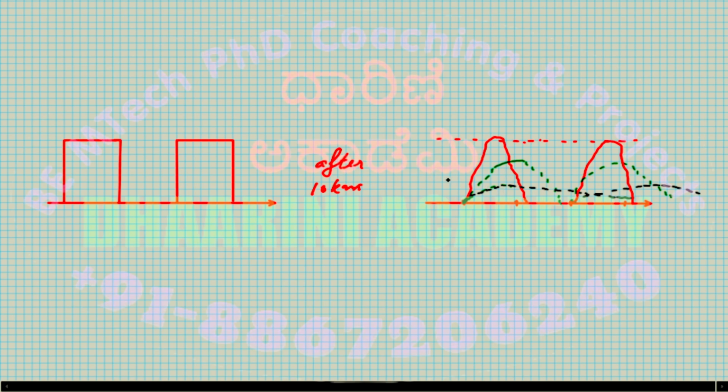Whenever this signal is given to the detector, it may have a threshold to compare. Say the threshold is 50%. If it is more than that, it is 1. If it is less than that, it is 0. Let us say. Now you see, your signal is not at all crossing the threshold. Correct? So everything will be detected as 000 only. So you lose your complete information.